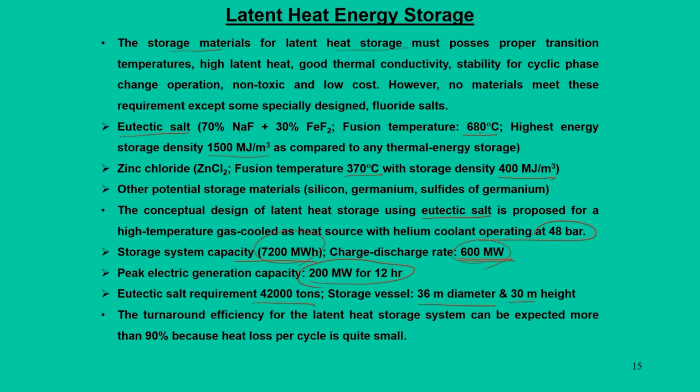So, it has to be contained in a high wall stress type of storage material, typically steel, and the cyclic efficiency or thermal turnaround efficiency would be close to 90%. So, this is just a conceptual design or idea for a latent heat based storage system, but it can be considered as one kind of storage unit.